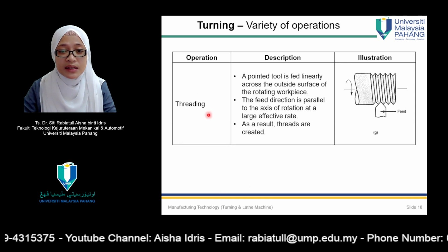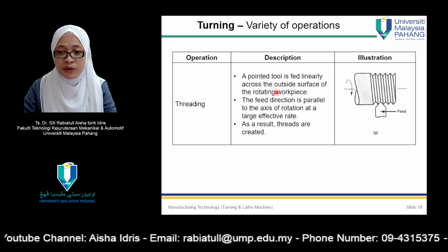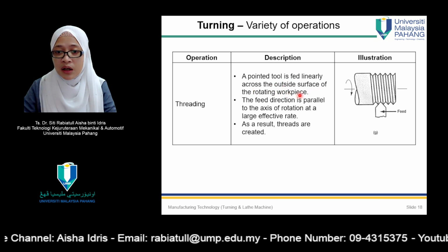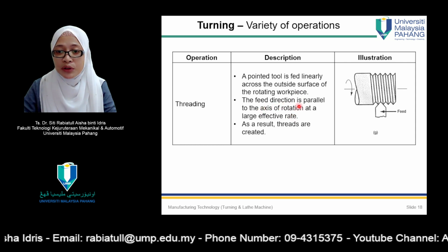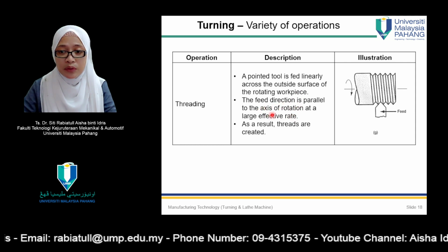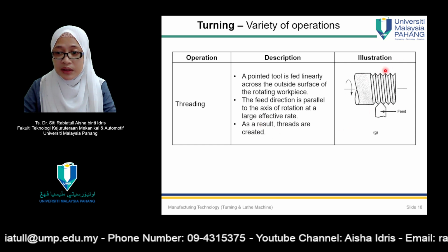And last but not least is thread. So a pointed tool is fed linearly across the outside surface of the rotating workpiece. The feed direction is parallel to the axis of rotation at a large effective rate. As a result, threads are created like this one.